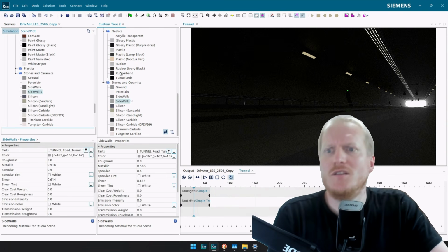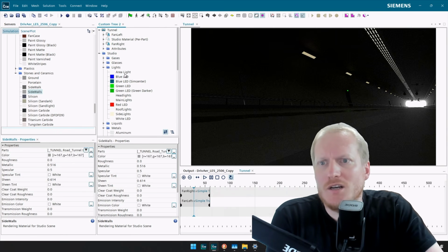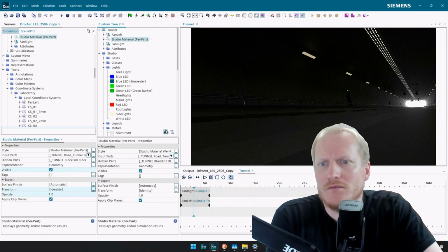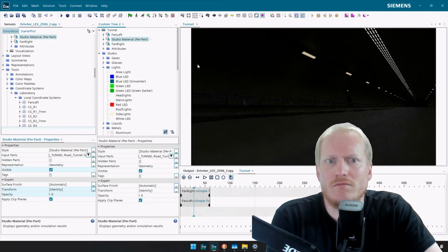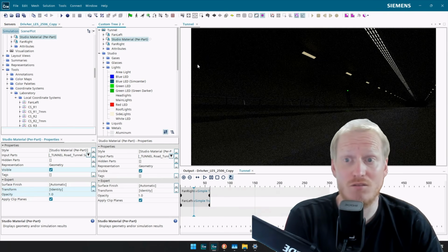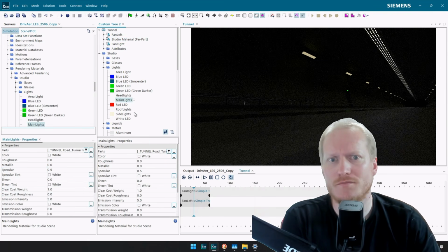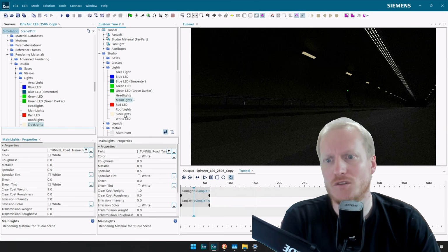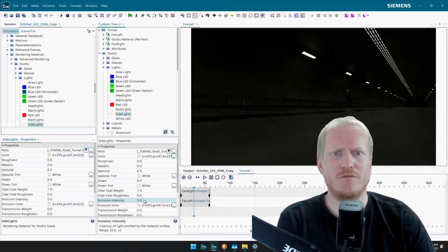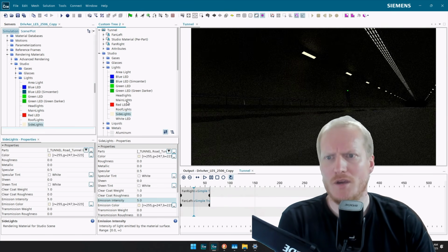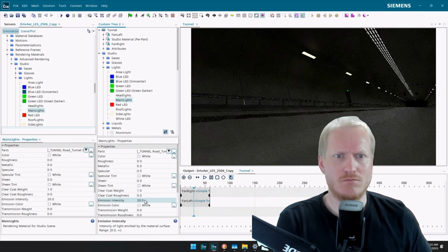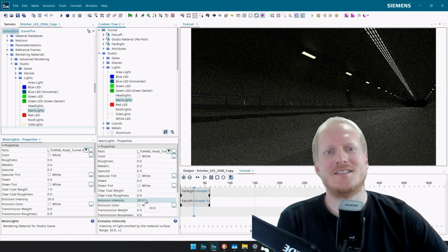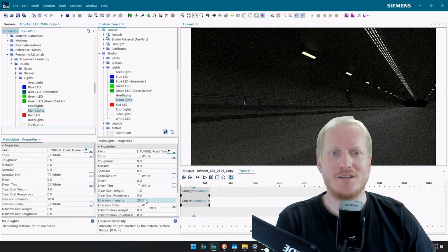Okay, our scene is too dark. And it even becomes way darker if I say, you, sir, are going to be here. It's very, very dark now. We can fight this. The side lights are not that bright, so we can say, okay, you're going up to 5. And main lights, you, good sir, are going up to 20. And see, that's adding some render time now.